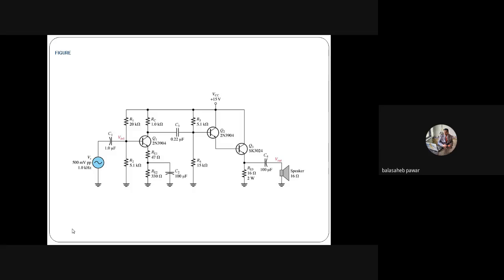But its wattage is shown very high, that is 2 watt. Just imagine a 2 watt resistor. Why is it taken as 2 watt? Because I already told you the last stage provides very high current amplification. So the emitter current of Q3 will be very, very high. If the selected RE3, 16 ohm, is of low wattage, then in hardware you will observe that the resistor gets damaged because of overpower dissipation beyond its power handling capacity.